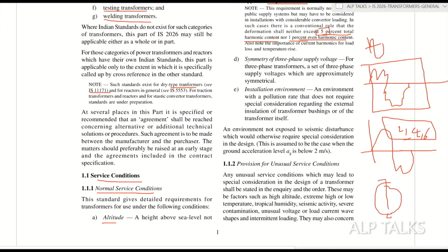For example, alternators have poles, fields and all. Whenever a field is applied and it is rotated by a turbine, electricity is generated. Whenever some pole is damaged, at that time we will get even harmonics here. So symmetry should be there. That's what even harmonics relate to.